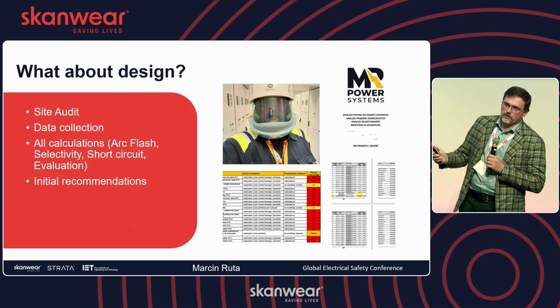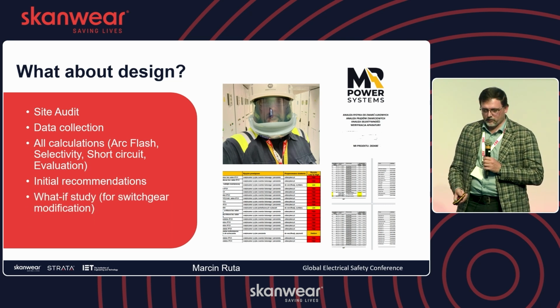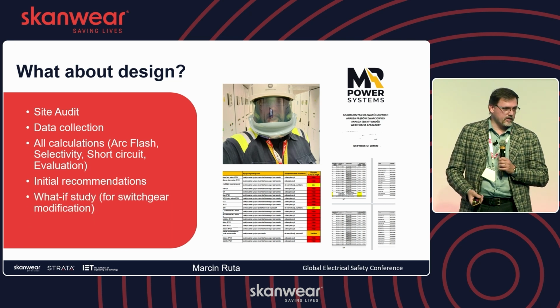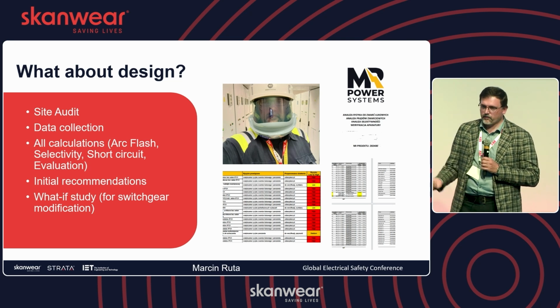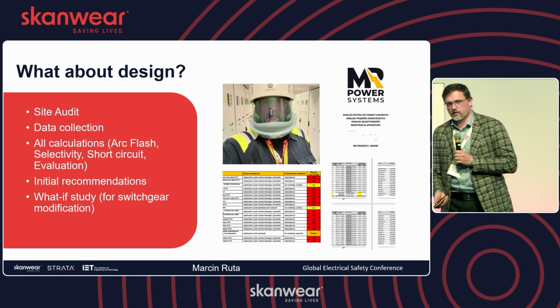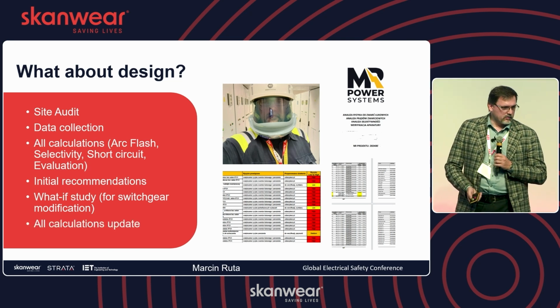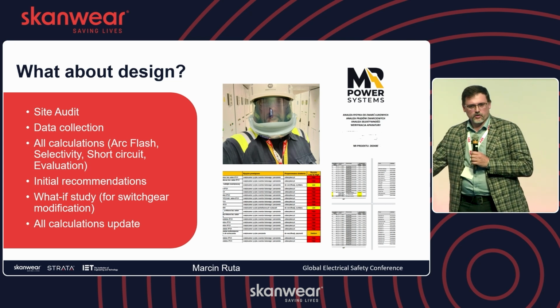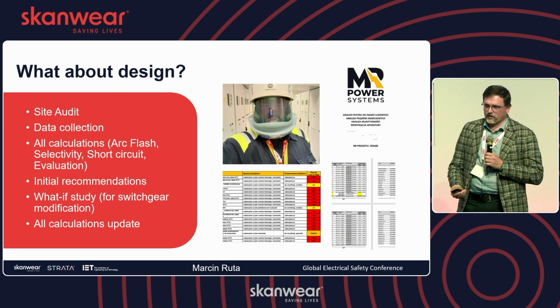Then, long story short, we came to the customer with the conclusion that, based on numbers, the best idea is to actually replace the main low voltage switchgear. And we did some what-if scenarios before we replaced it. That was the early phase, the cheaper one, considering replacement of the switchgear. And at the end, we did all calculation updates in the commissioning phase after they actually installed it, because there were some changes, apparently, as far as I saw on site.